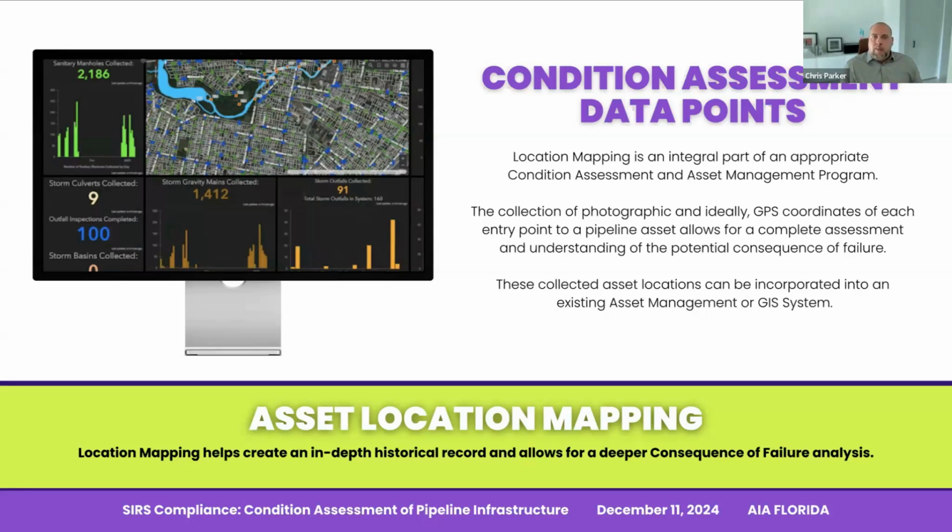If you're working with a reputable pipeline assessment contractor, most will have these technologies already built into their camera systems or readily available, with plotting a starting and ending point so you can truly understand where that pipe snakes between the top of a structure down to the bottom floor. That is essential, because not every pipe is vertically straight. Not every horizontal pipe is running straight as well. There are a number of 90-degree and 45-degree bends that happen within this piping infrastructure.